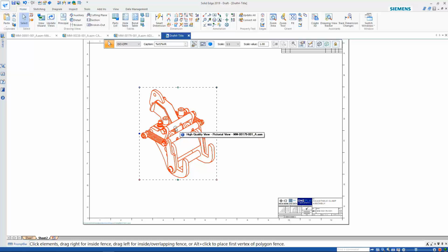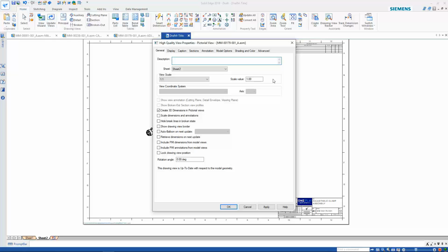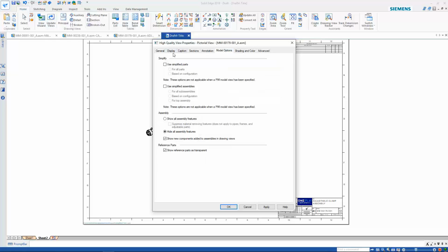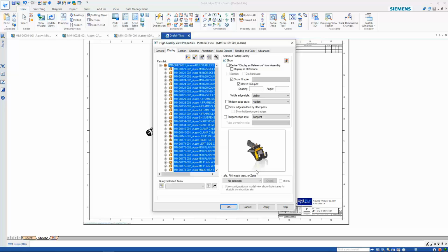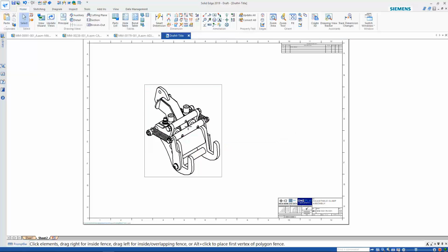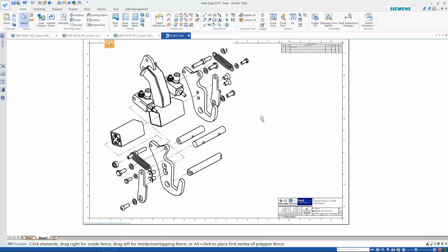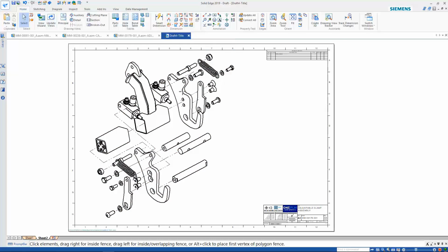Okay. So on here, I'm now going to find the exploded view. So the exploded view has already changed. On the display tab, I can find any display configurations, and I've already got an exploded view version. So when we do the auto explode command, it uses your assembly relationships and just creates offsets on those assembly relationships. So as long as you've built that part nicely, it's going to look quite nice on the explode. So we've got that explode, fits quite nice.